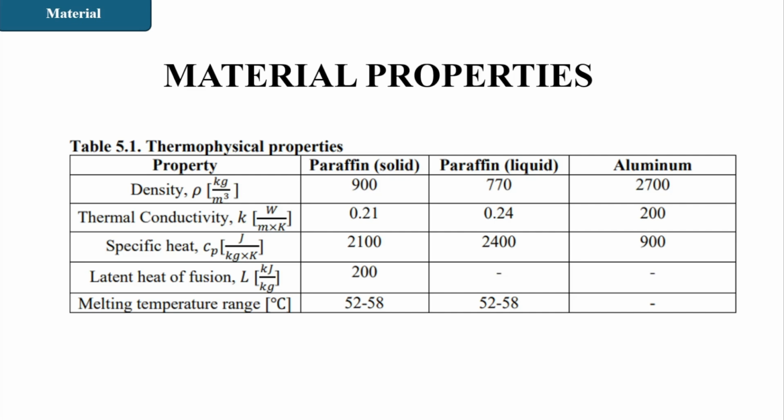On the other hand, aluminum behaves more like the opposite. It conducts heat extremely fast, but it also adds thermal mass. So fins can spread heat, but they also require energy to warm up. This contrast is exactly the design trade-off we are trying to understand under transient heating.